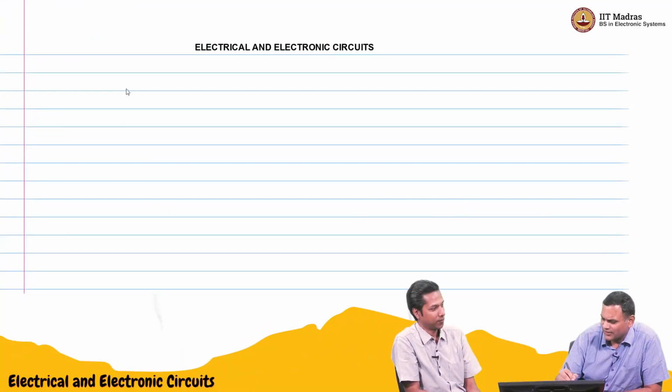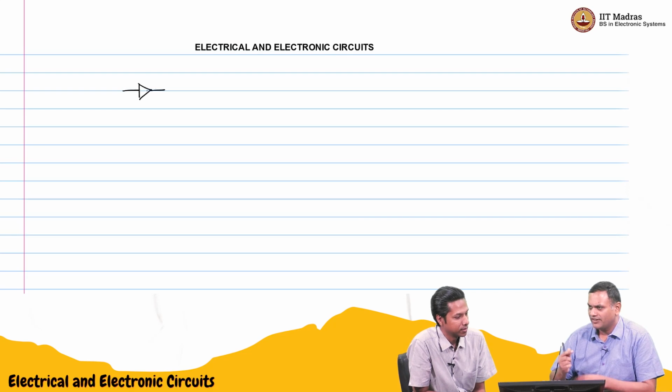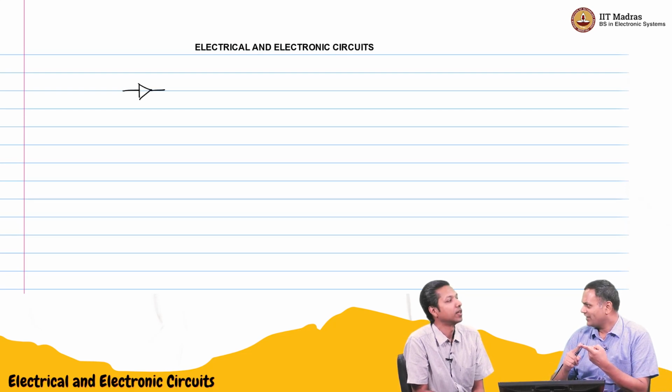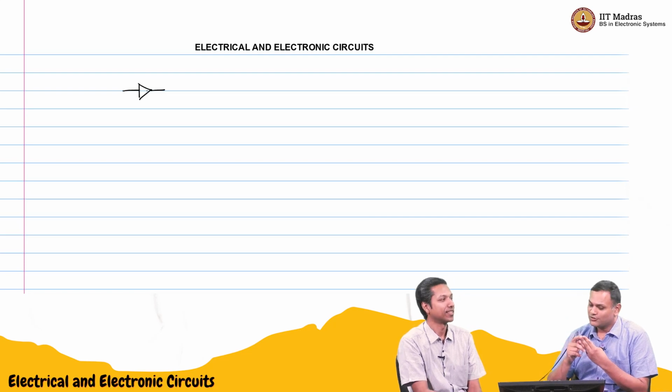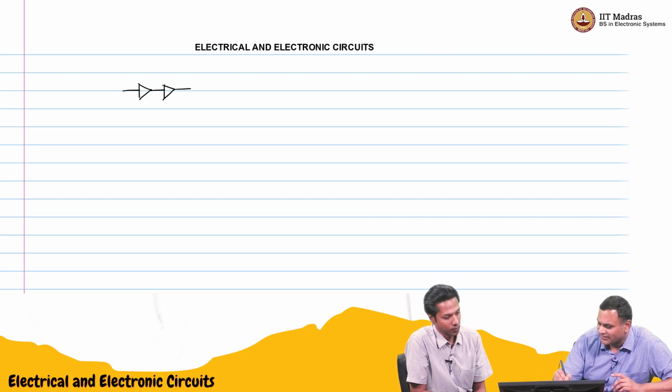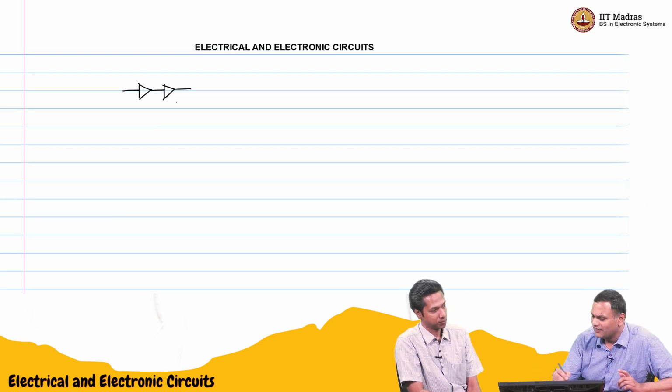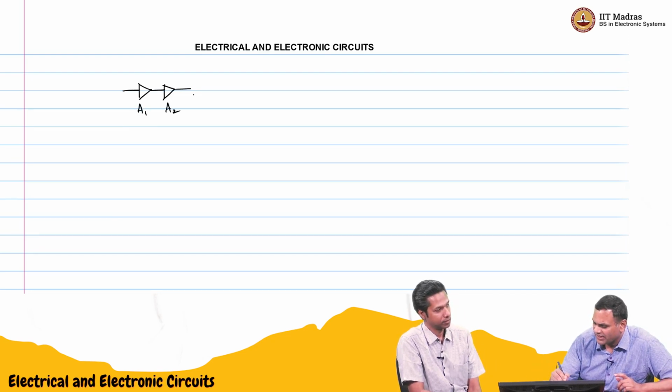Actually, this electronic circuits, the amplifier using BJT, MOSFET, all those are very nice. And you were also mentioning, if you want more amplification, I can cascade: one amplifier followed by the other one, and so on. We looked at how the common emitter gave us negative gain. Common base gave us positive gain. Common collector gave us no gain, but the ability to drive something. Common collector can also act as an output stage, and we can cascade many amplifiers if we want.